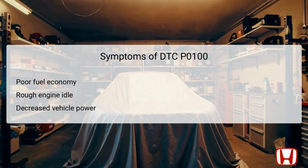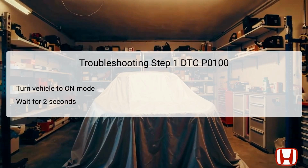The initial step in troubleshooting DTC P0100 requires the vehicle to be turned to the on mode, which is crucial for the Powertrain Control Module, PCM, to initialize communication with the sensors. Once the vehicle is in the on condition, it is important to allow a wait time of at least 2 seconds.